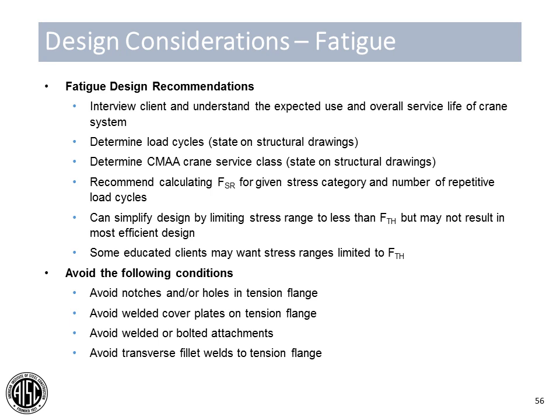It would be recommended to calculate the allowable stress range for a given stress category and design for that, but you can simplify your design by limiting the design stress range to the threshold stress range. However, this won't result in the most efficient design, and a lot of times you'll actually have clients that want you to design to only that threshold stress range.